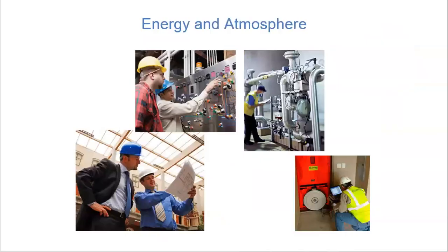These are some of the examples that I can show you. What do we mean by commissioning? All these, for example, mechanical ventilation systems, your furnace, and any other smart building features for your building have to be tested, verified, and commissioned before the building is actually operated. And then they need to be checked after occupants start using your building as well. Again, this is for new buildings, new construction.